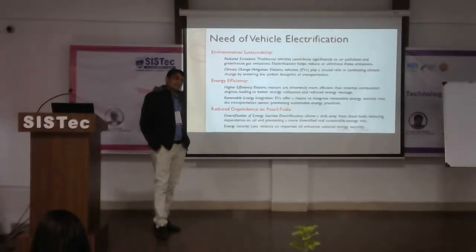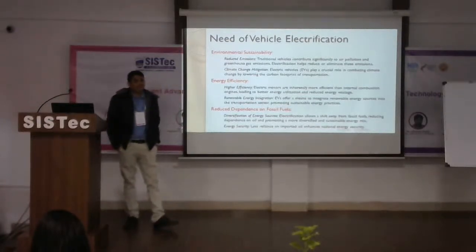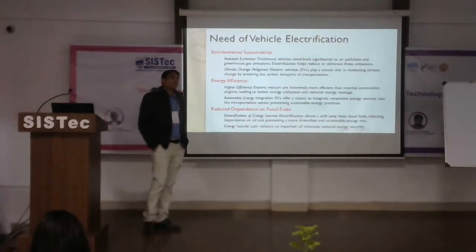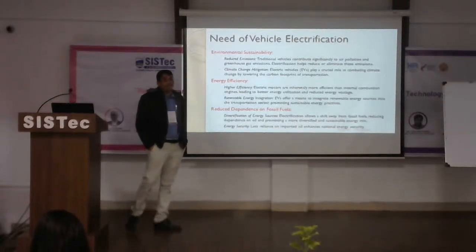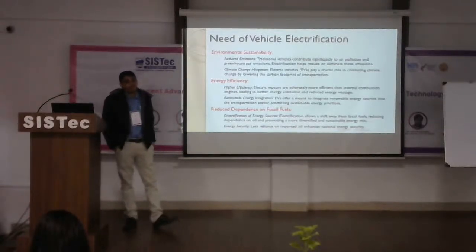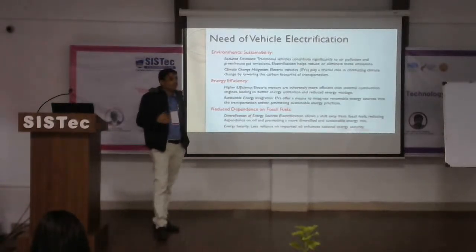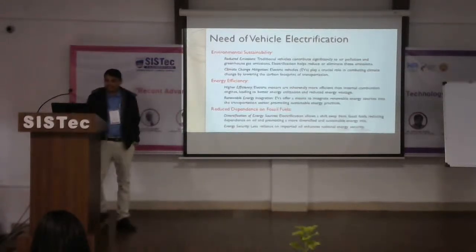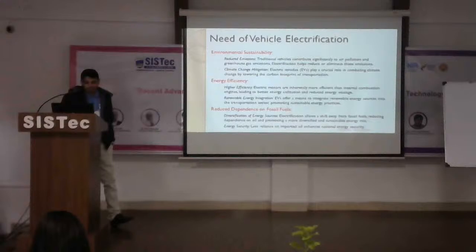So yes, that is because pure hydrogen is required and it is converted to electricity, and that electricity will require a propulsion or rotating motion. So we require a motor, and that motor shaft will connect with the IC engine. So this type of system will be lengthy and complex, and when the system is lengthy and complex, efficiency automatically will be reduced. So that is the thing with the energy efficiency.